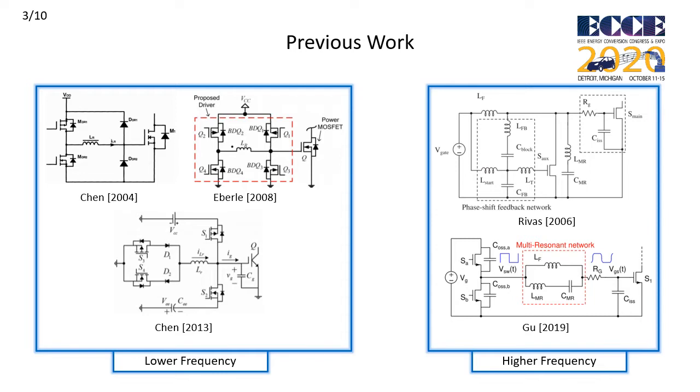Some of these approaches enable voltage swings that extend beyond the rails of the power supply provided to the gate driver. So this allows for low voltage, high speed driving devices to be used in higher voltage driving applications, such as silicon carbide, where you could potentially use a 5-volt supply to drive a gate voltage of, say, plus 15 volts to minus 5 volts, for example.